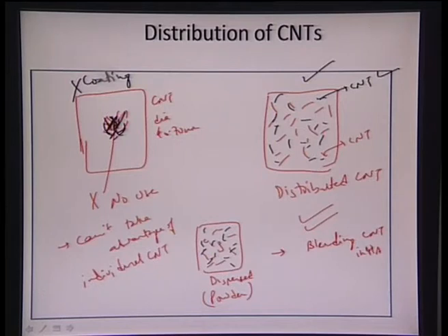If we are able to achieve this blending in hydroxyapatite itself, we think that the same phenomenon will get retained even after plasma spraying. So it becomes highly essential that we are able to disperse the carbon nanotube in the hydroxyapatite matrix at the stage of blending itself. If we are not able to achieve dispersion of CNT during blending, then the agglomeration of CNT will remain even during the plasma spraying process.